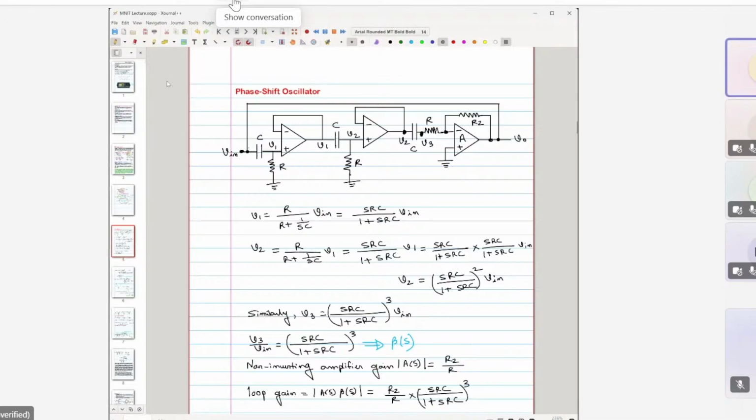So this is the phase shift oscillator. This is actually the same circuit that I have drawn in the last page. But there we used only one op amp, and here you can see we have used 3 op amps. But do not worry about it. See how these op amps are used? These op amps are basically used as a buffer, right? See, the inverting terminal has been connected with the output. So that means the gain of this part is actually 1. And why do we use it? I will discuss this after some time.